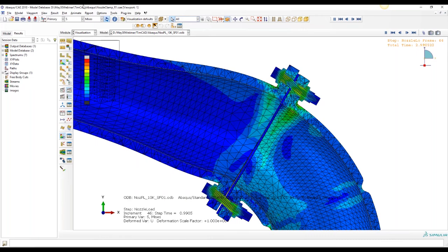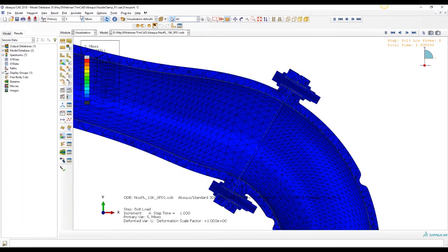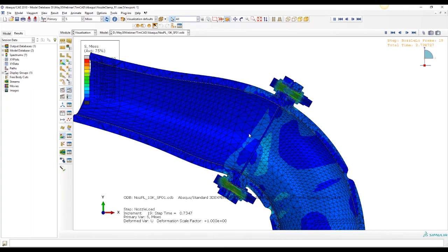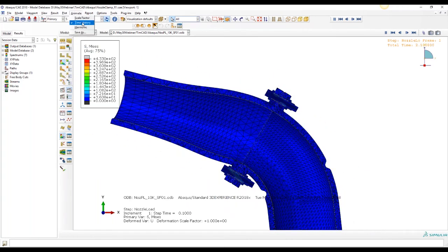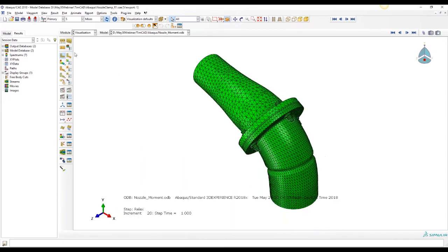This happened to be no friction set up in the contact condition for the gasket, so it's not really bearing any load. So as you'd expect, all the load of that assembly goes into the shear of those bolts.